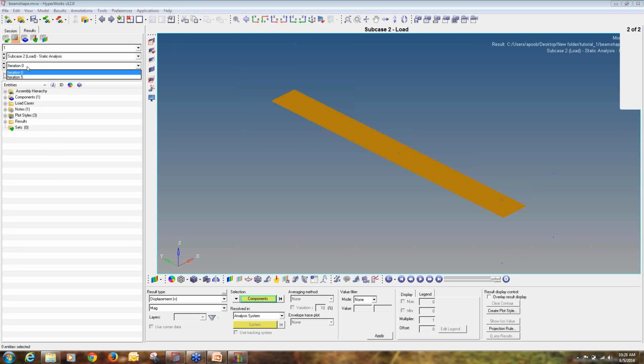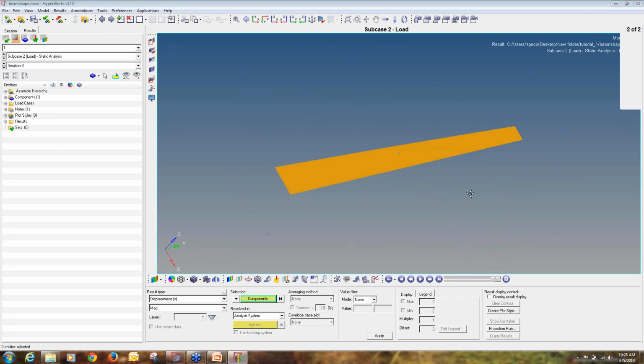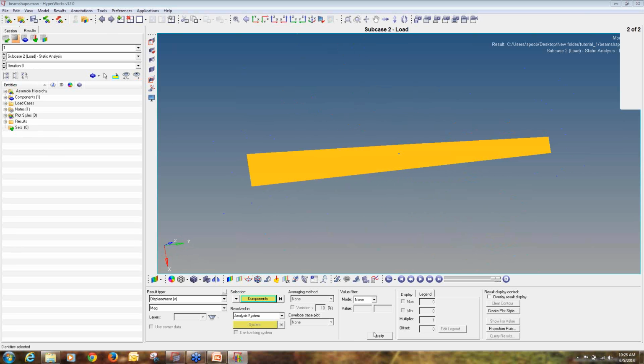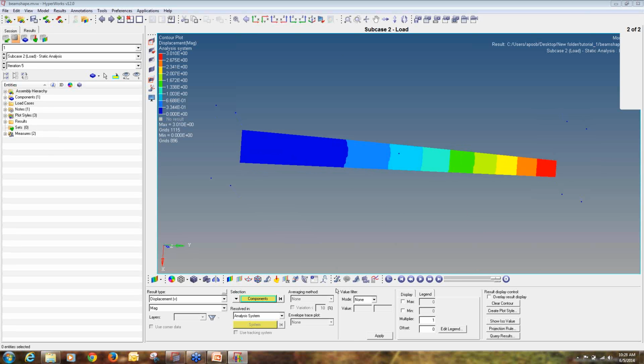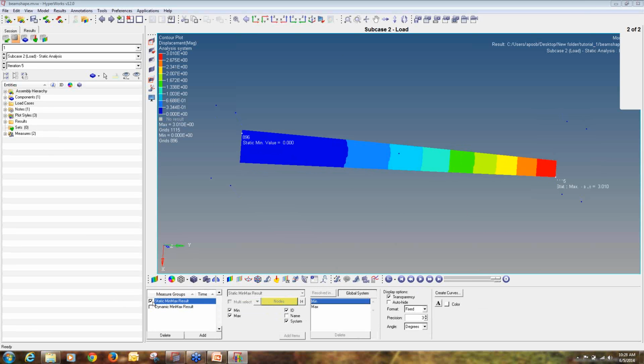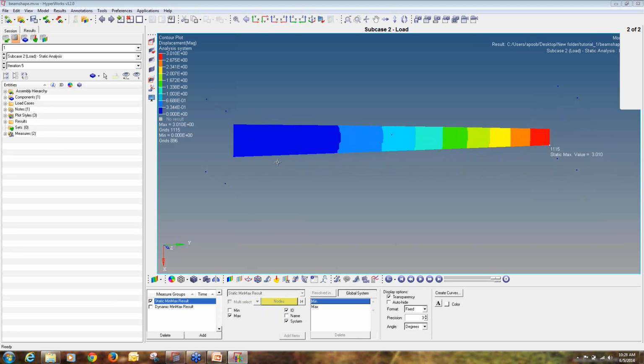And if we click next, so this is the shape change and the displacement values. So you can see the displacement is not exceeding 3. It is 3.01, which is nearly the 3.1. So while changing the shape, we have achieved the desired constraints. So in this way, we can perform the shape optimization by providing different shapes, appropriate constraints, and performing the analysis. So with this, I have ended the first tutorial.